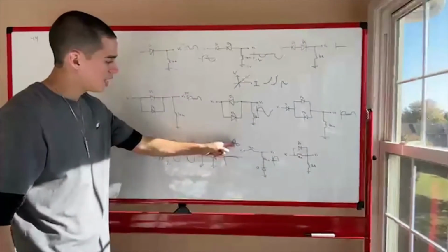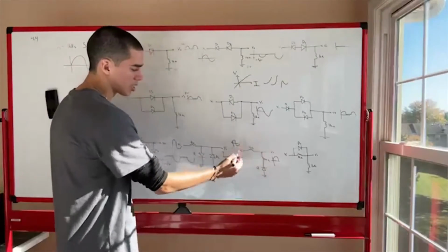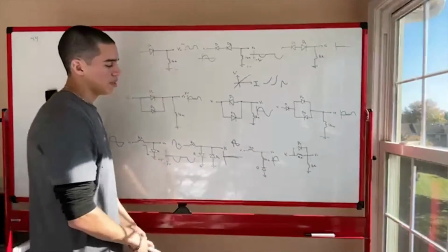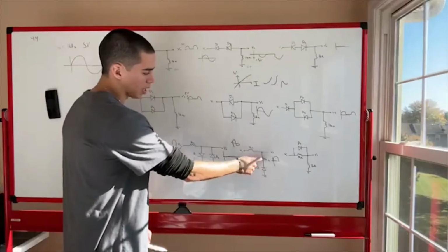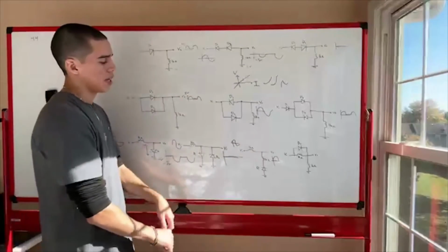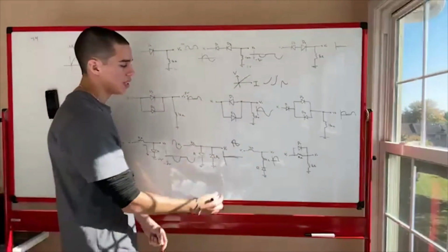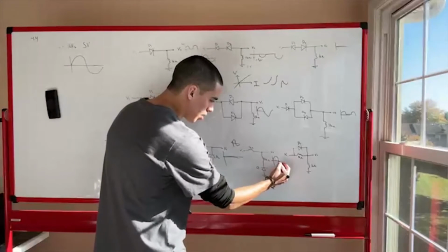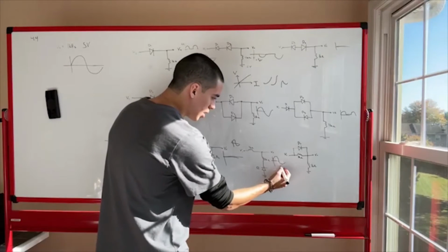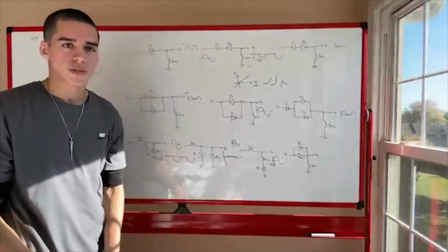And then during the negative part, this would be smaller than this, so it would conduct current. And you would see if this was a short circuit and we're conducting from 0 to negative 5 volts, we have 2 resistors creating a voltage divider, and so we go down to negative 2.5 volts instead of 5 volts.